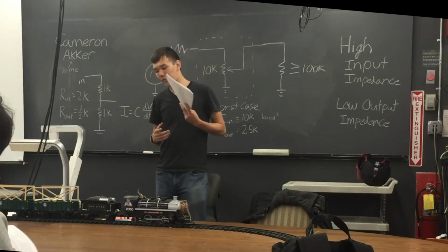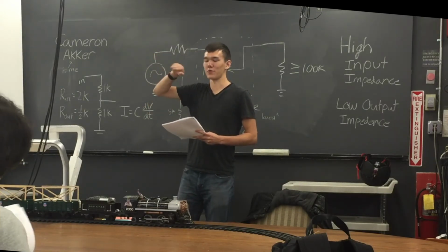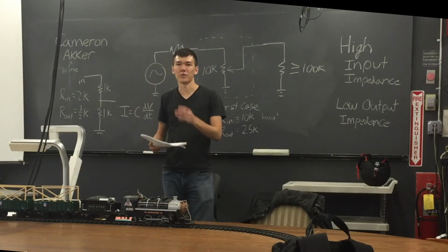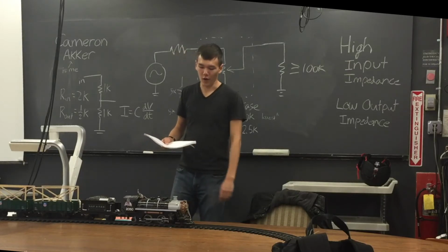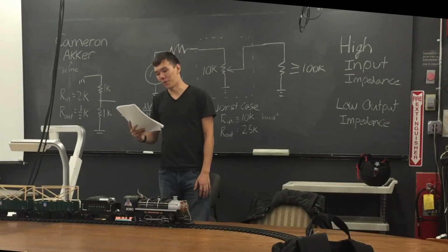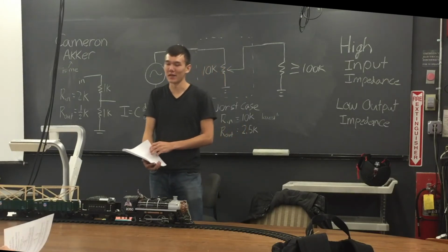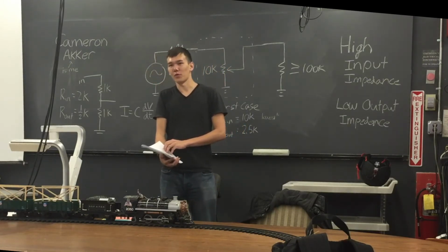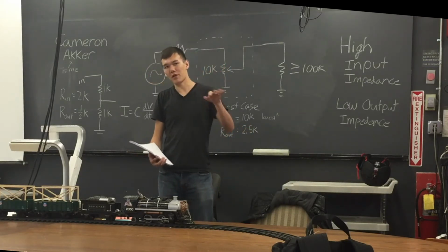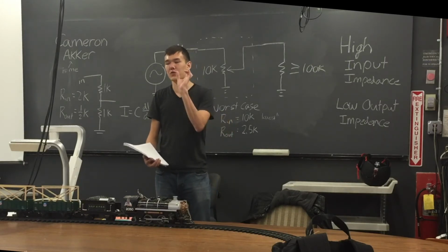So if you ever get a waveform that is just a little bit too fuzzy, like you can see where the line should be, but there's a lot of fuzz around it, plug in a decoupling cap. There's a little ceramic, little circle clay dot looking things. Those are really useful. Blocking capacitors are also a topic that I don't think Tom talks about that much in lecture. Essentially, the capacitor takes the differential of what's coming into it. So if you have a signal that's varying and you want to knock out any DC component, in other words, you only want the change, you can just put a capacitor right in the way.